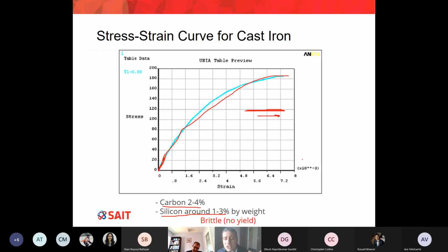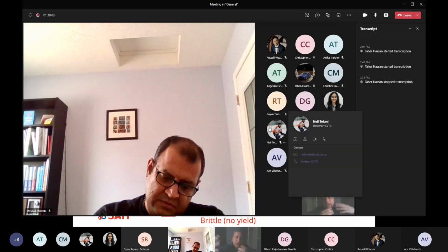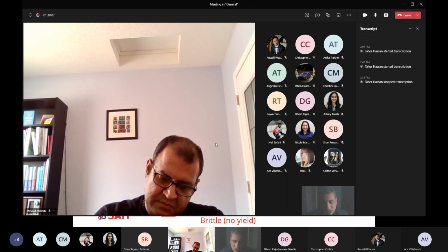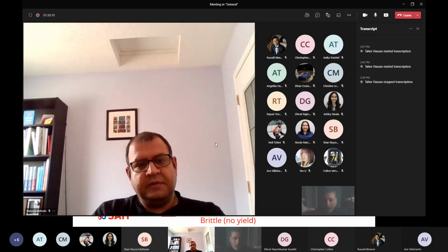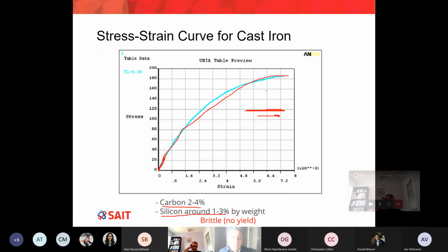However, for design purposes, people do want to see a number, which is not really the yield, but for taking a factor of safety from the ultimate. So cast iron does not yield. Mild steel does. Cast iron is brittle. Mild steel is ductile, so there is lots of elongation because we have the yield. Although I just said there is no yield, in order for you to find an equivalent value of the yield, you do the same thing as mild steel.